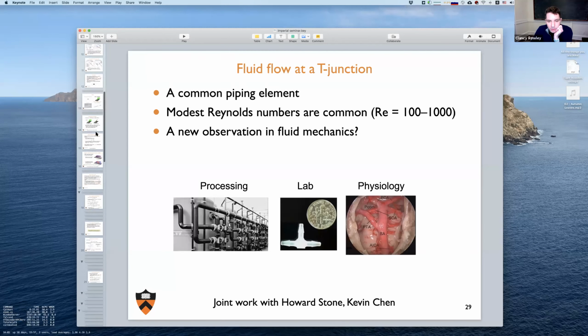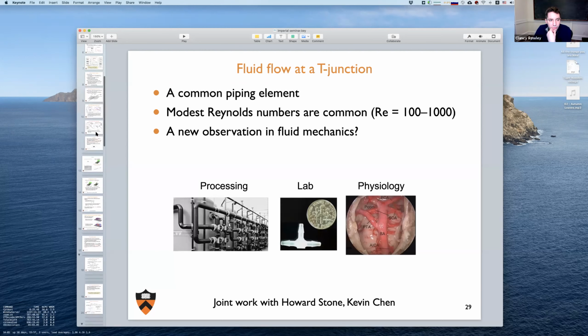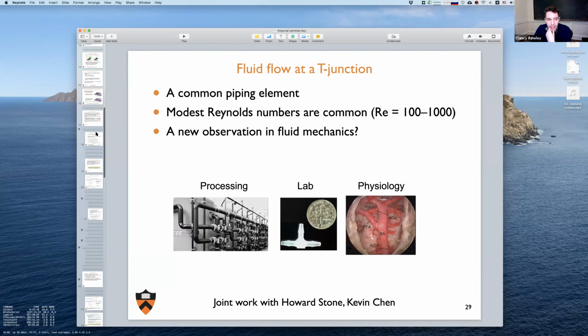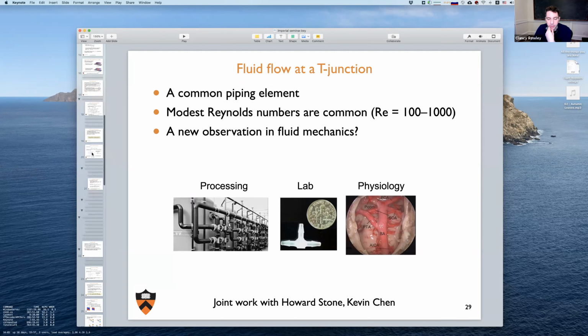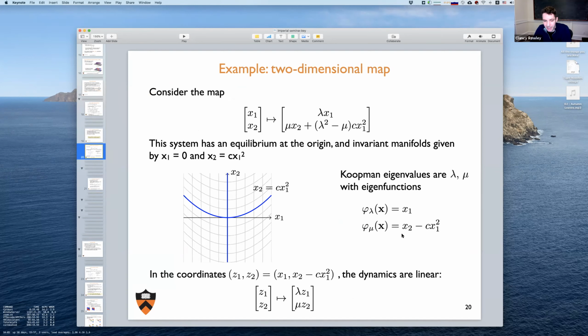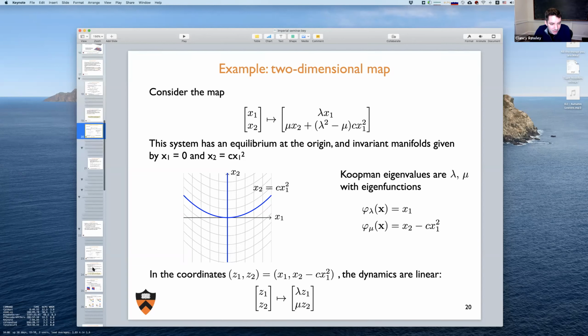Yeah, I wish I knew. I think there's no great general procedure for doing that. To be honest, there are basic things you can do. If you know something about the state space, you could in principle choose good things. In this example, we knew what the eigenfunctions were, so we knew what terms to choose. Often what makes sense is to include just monomials, like polynomials in the states, just because you can approximate smooth functions with polynomials. So that's a starting point.